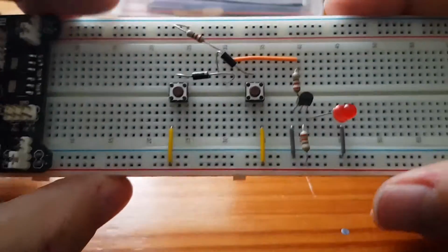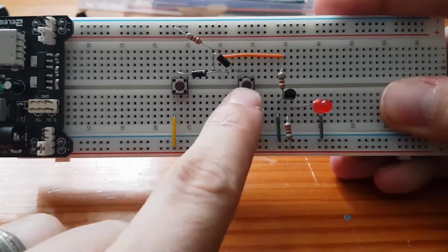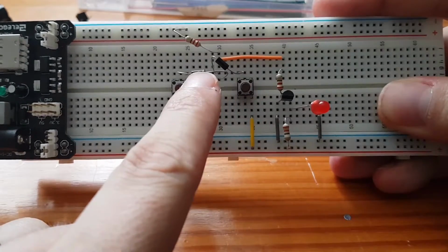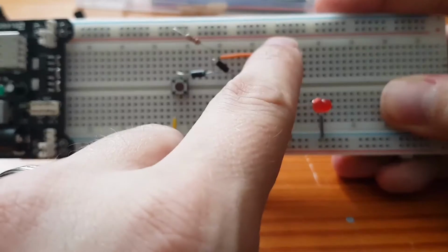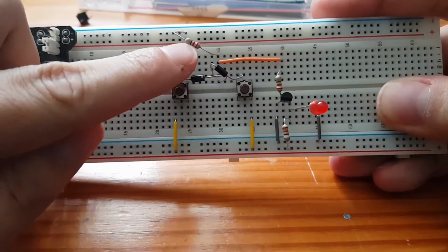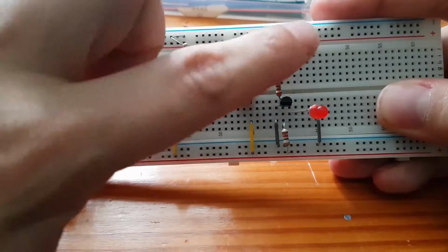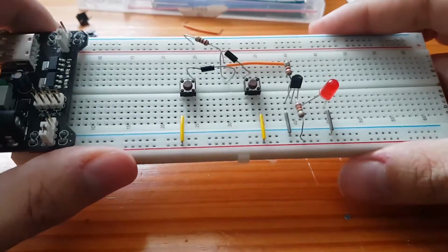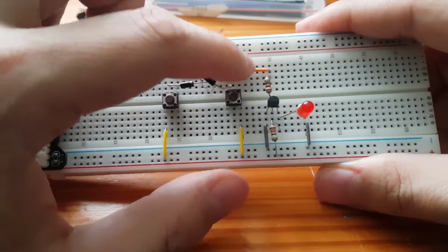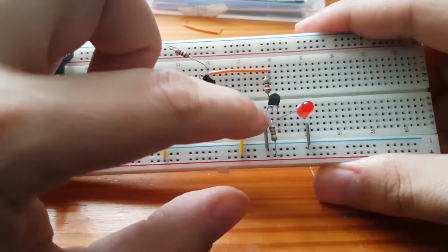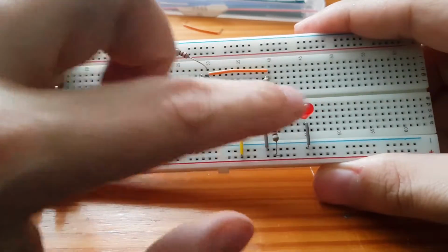Okay, and here's our NOR gate, as you can see. So remember last time we built it with two inputs, two diodes. These are connected to 5 volts, so we input 5 volts into here. It will go through to our output. Up here we've got our pull down resistor. So when one or both of these are on, then the output will be up or high. Now the thing with this is we've connected that to an inverter now. So when this is actually low, the inverter output will be on. And when this is on, the inverter output will be off.